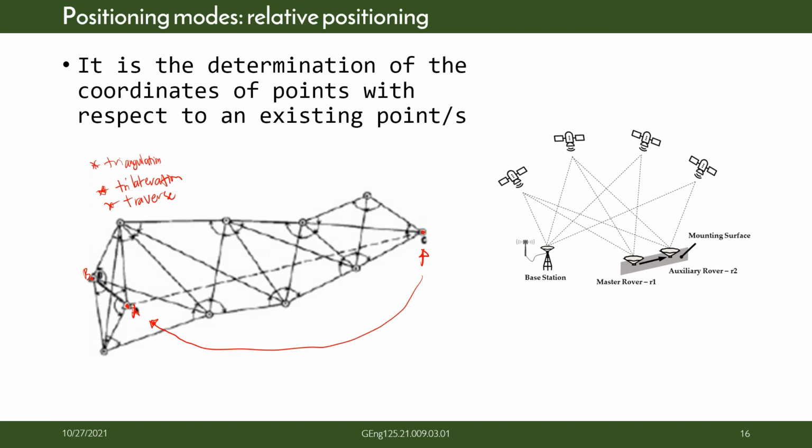So you have this figure, then they employ strength of figure, or the method in establishing point C can also be combined: triangulation by angles, trilateration by distance, and traversing, both mixed.